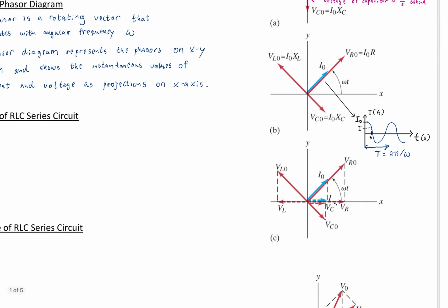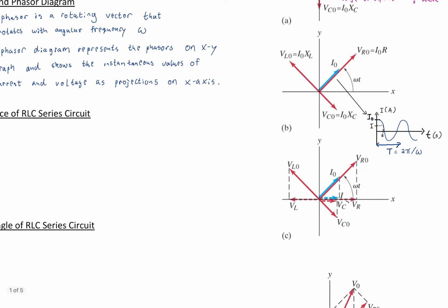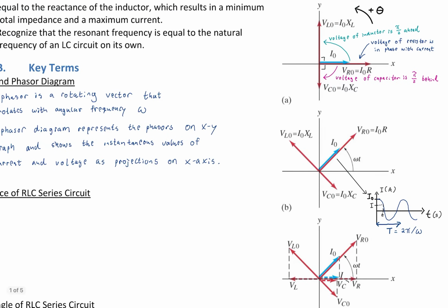Let's show this in diagram C down below, right? So all we're doing with these diagrams is, I showed the basic phasors for an RLC circuit. These are the only phasors that we'll discuss, okay? The one current phasor and then the 3 voltage phasors. Then we rotated them because we let time pass, just an arbitrary choice of letting it rotate about 45 degrees, all right? Or pi over 4 radians.